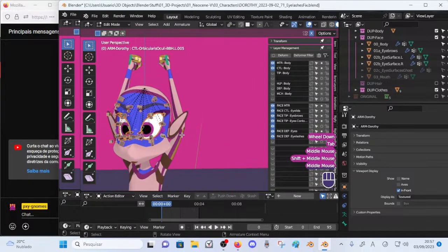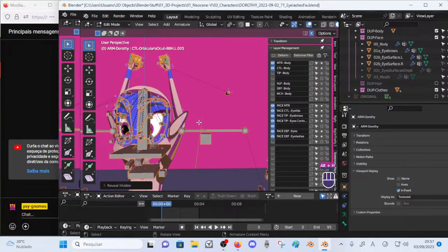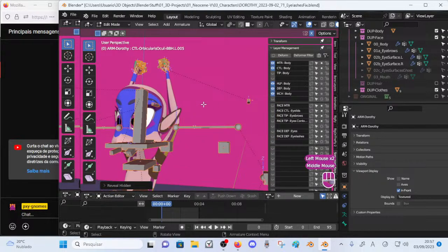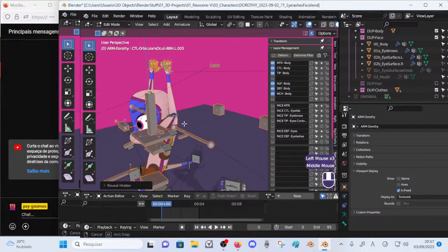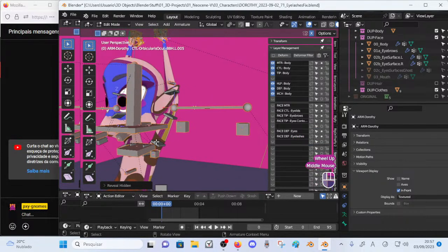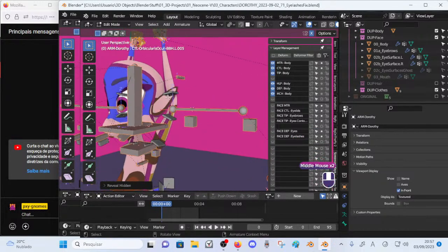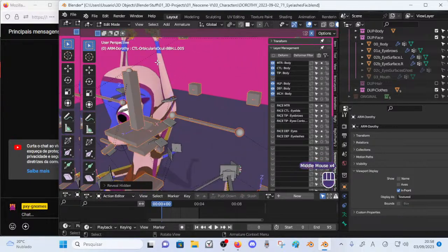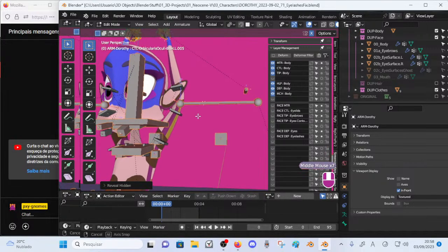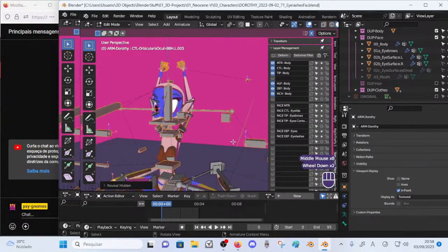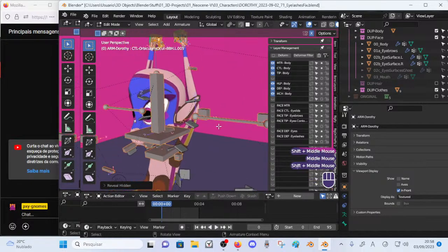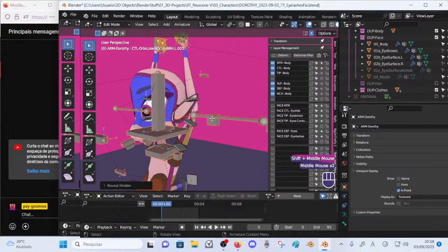the arms, because what I found out, and this is important, is that the problem I had with the arms in that rest position is because I have bendy bones. This pose actually required a lot of twisting and detwisting of the orientations, and this was a complete mess for the original arms that I had, the bone structures especially, not so much the mesh, but the mesh in relation to the bones and the bones twisting.